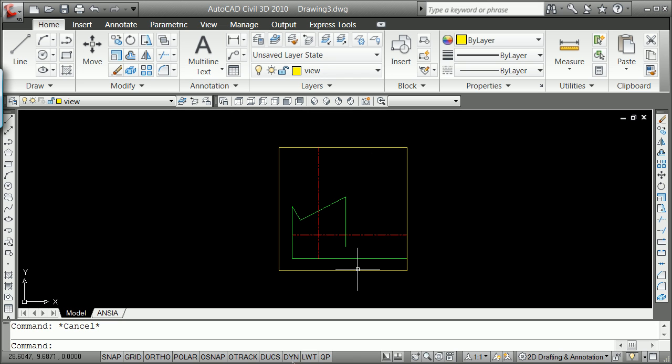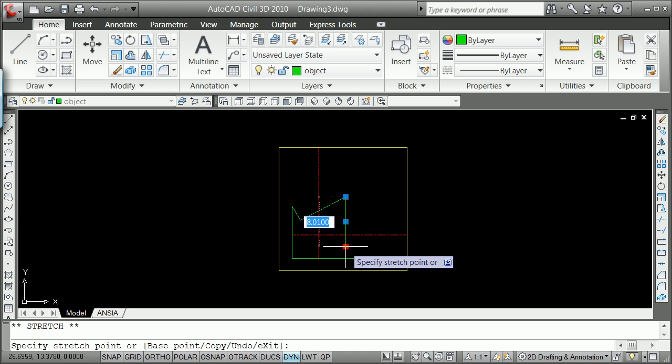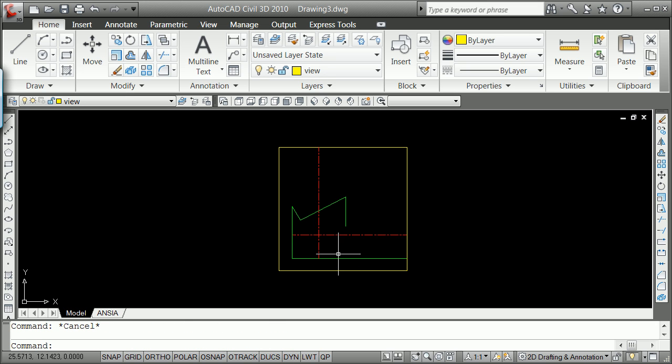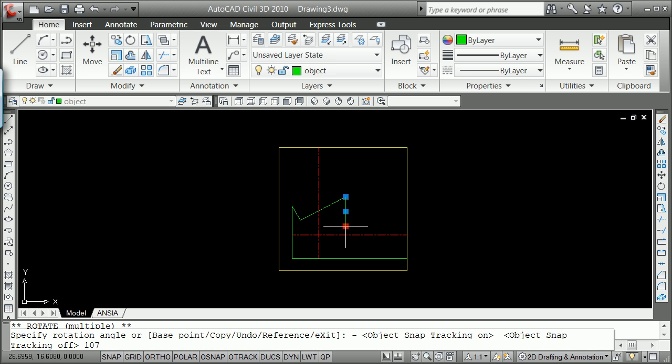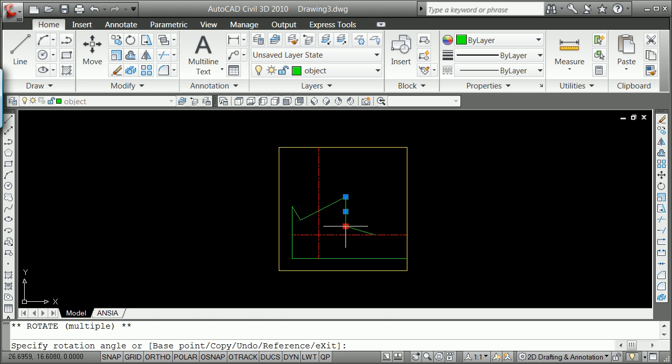But again, now you turn the dynamic on, you go to the thing you want to change the length of, you left click the end you want to change, and then in this case it is 4.78. DE is 4.78. Hit an escape key, turn the dynamic off, left click, spacebar, C for copy, -107. It turns it there. Escape.